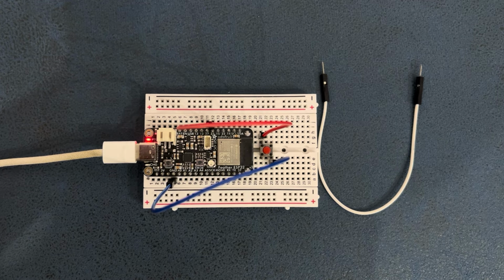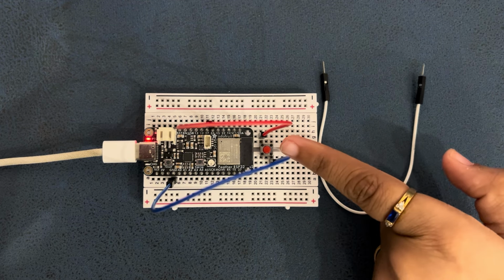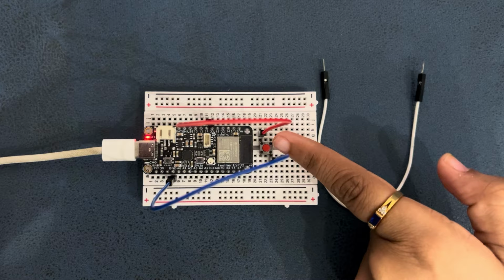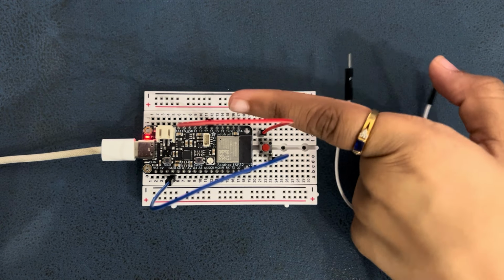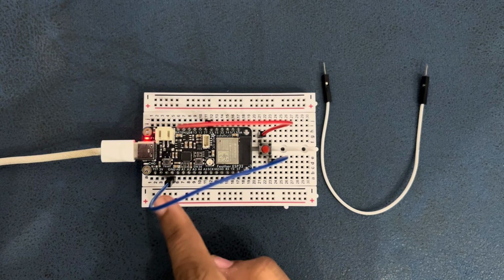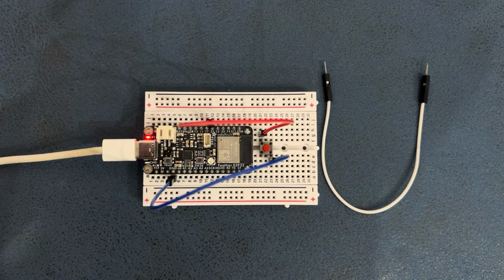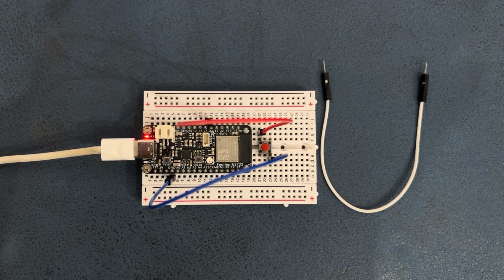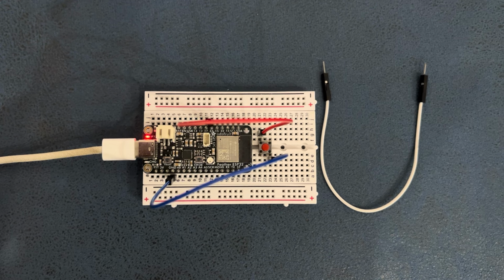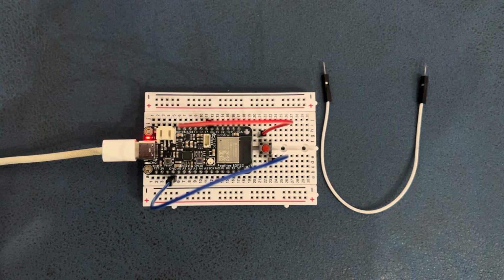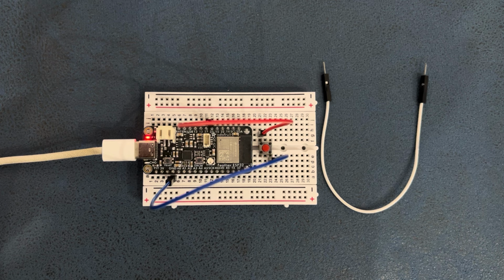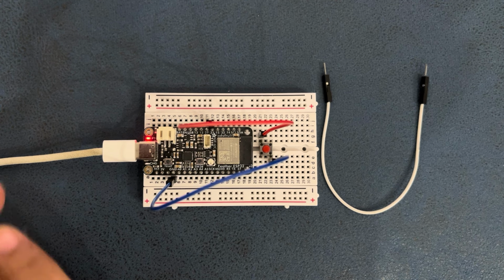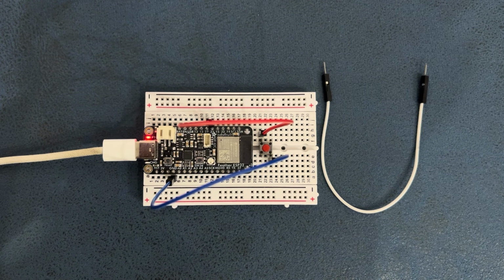so that when I touch it, the capacitance changes, which allows the ESP32 to detect the touch. Now for the push button over here, which is the wake up source, one side of the button is connected to GPIO 33 and the other side is connected to the ground. The pin is configured with an internal pull-up resistor. So when the button is pressed, the signal goes low, which triggers an external wake up.